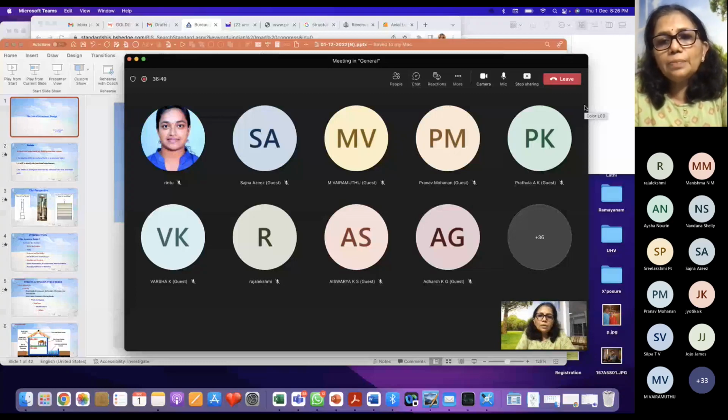What kind of stress is developed at top? Tension. Whereas in a simply supported beam, what kind of stress is developed at top? Compression. Excellent. So depending upon the support condition, the behavior of the structural element changes.